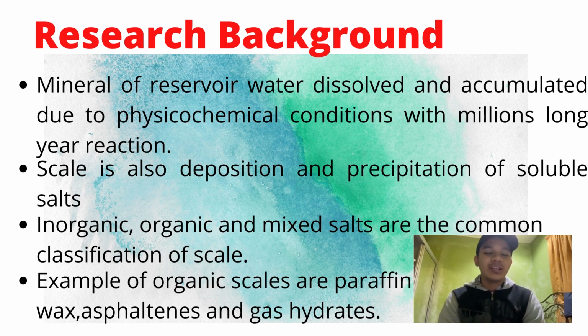It is a dissolution and precipitation type of reaction. There are two classifications of scale: inorganic and organic scale. But there is also mixed salt. Mixed salts are the most difficult scales to be handled. Examples of organic scales are paraffin wax, asphaltenes, and gas hydrates.